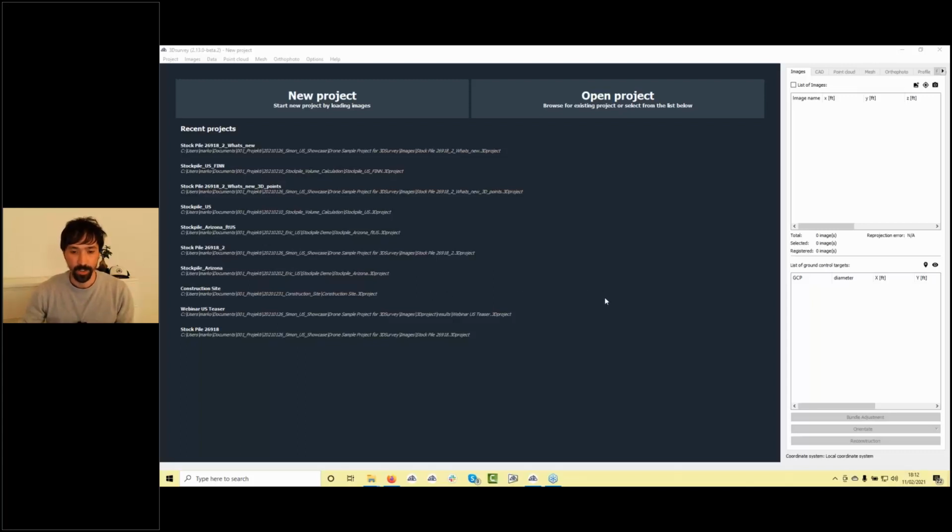Okay, another question from Eric Evans. Have you processed any data from the Matrice 300 with a P1 camera? Not yet. Oh, we actually did, but I don't have results. We got the first data set yesterday. My colleague was on the webinar from DJI with a P1 camera. I would say the Phantom 4 RTK still stays the best selection for surveying purposes because it's small, it's reliable, powerful. The camera is good enough.